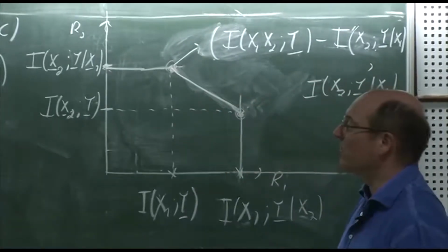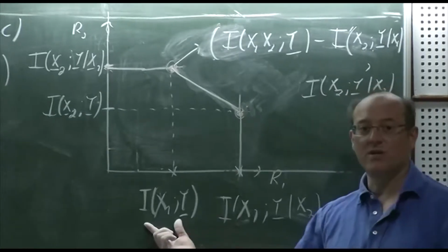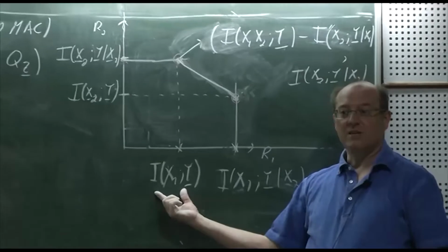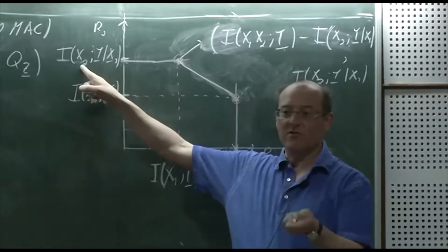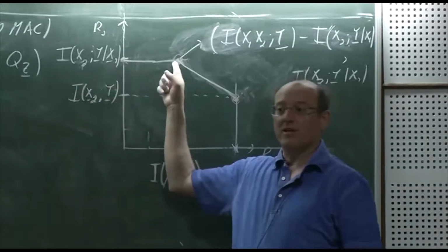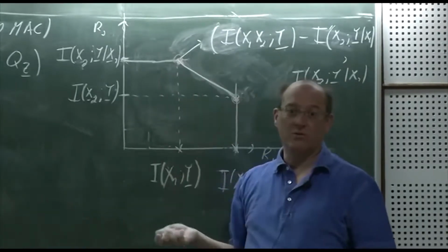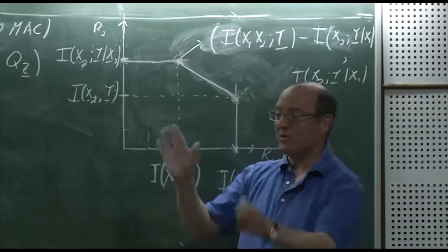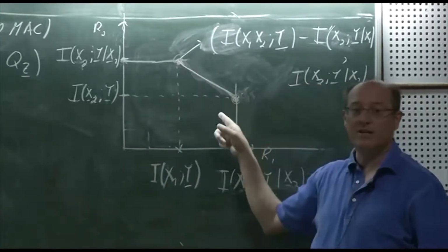So what I'm going to do at the receiver is first decode this one here by treating the interference due to the x2 as noise. There's no beamforming because it's just a scalar. Subtract it off, and then I operate at that corner point. And then I can do time sharing to operate in between. Right, so that's one way to do it. Or alternatively, you can do that shifting in time that we just talked about. Then you can operate anywhere inside here.